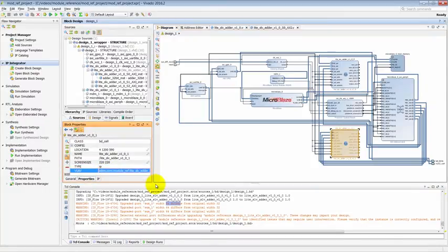The RTL module has a VLNV, as you can see in the property window here. However, a user does not have control over versioning of the RTL module. These versions are maintained internally by the tool. The RTL module definition cannot include other IP definitions, netlists, nested block designs, or another module that is set as out of context inside the RTL module.